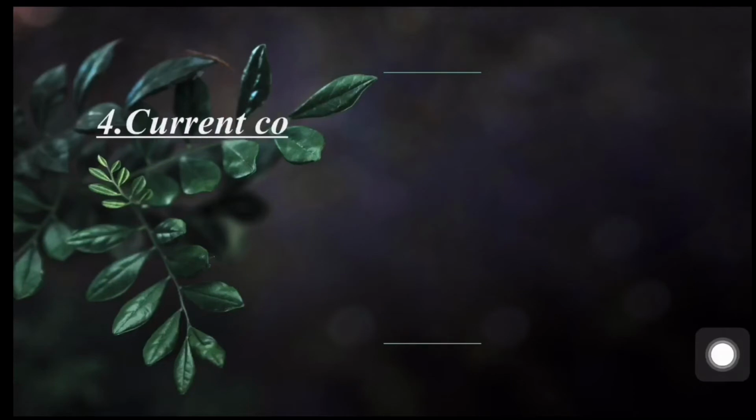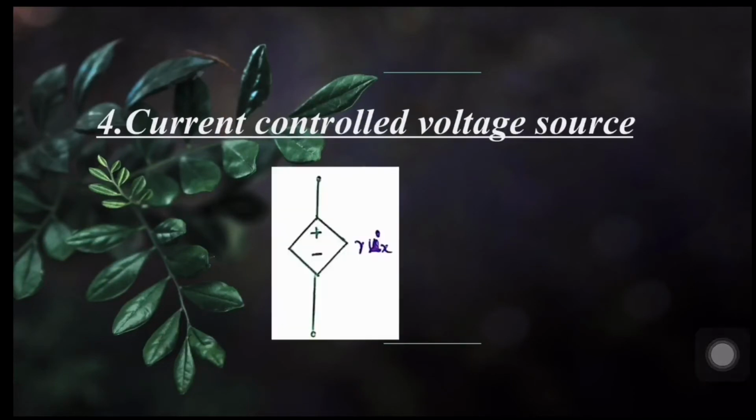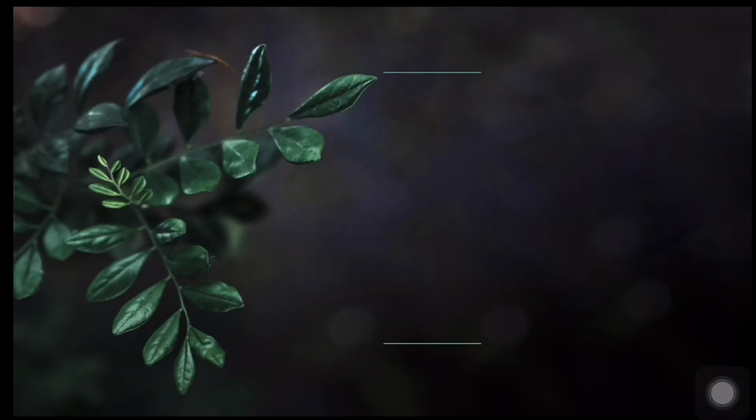Finally, we have current controlled voltage source. This is the symbol and R into Ix is the source quantity where R is a constant and Ix is the controlling current that is defined at some other location in the network. Thus, here we have a voltage source that is controlled by a current. That's all I want to say about dependent sources. I think it is better to understand how to perform mesh analysis in a network consisting of dependent sources with the help of problems. So let's move ahead and solve some problems.